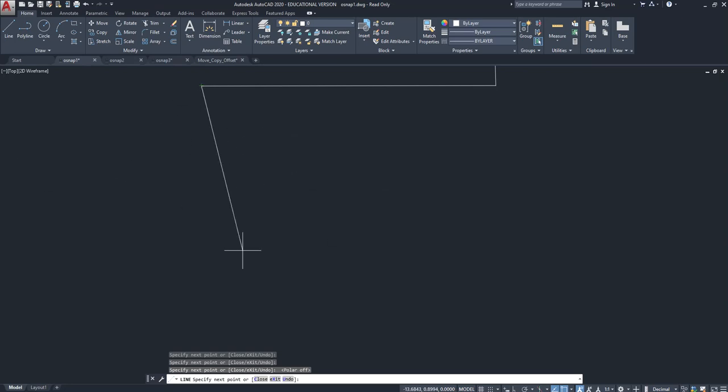So if I'm drawing like this, just straight lines, I hit F8. See immediately my screen changed a little, right? Move in this direction, click, F8 to turn it off, click, F8 to turn it back on, and you'll see a perpendicular snap pop up. That means it's going to intersect perfectly at right angles and be straight. Click, escape.